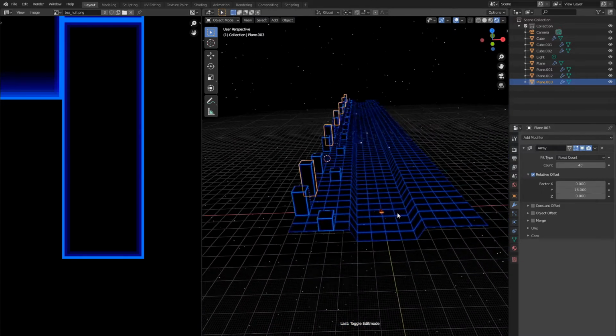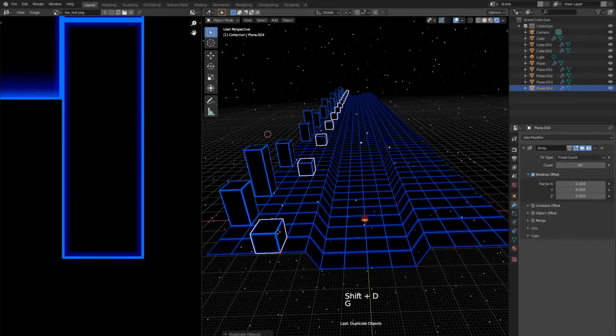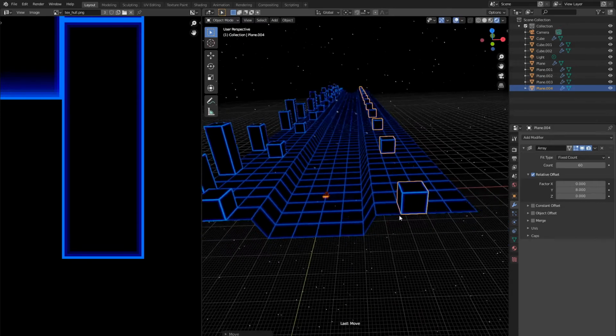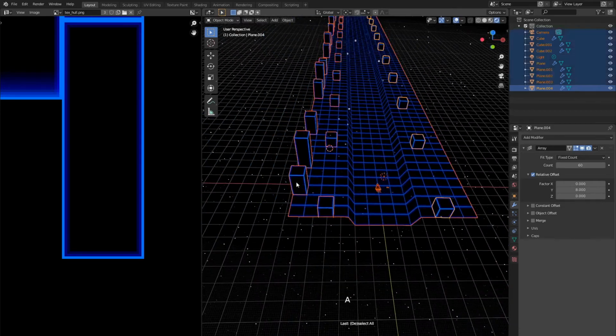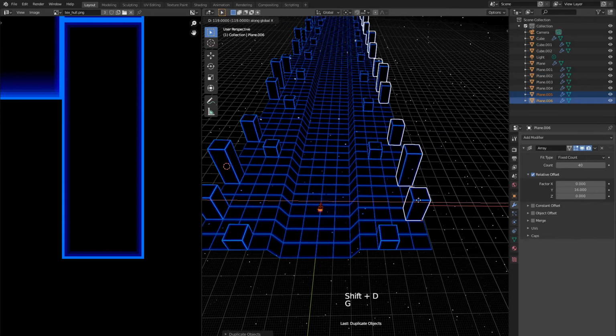Okay, now let's copy what we have on the left runway side and move it to the right side. Why wouldn't we just use the mirror modifier we used before? That's because we'll have to put origin of each object to the runway center for this to work. It would be weird and that's not something we want. So this time just copying meshes is the simplest way.